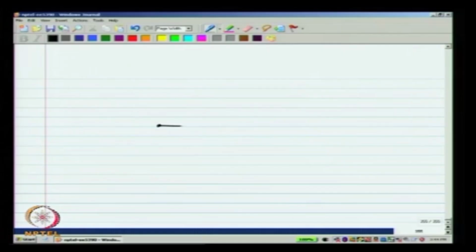Now, like before, like with the single ended fully differential op amp, we have a choice of common mode feedback circuits available. Okay. Now, as I mentioned, there is just too much variety and I will not be able to go through all of them, but I will discuss one more interesting common mode feedback circuit that can be used for the first stage in this case. Okay. It will become clear why it is suitable for the first stage. For the second stage, we will use the conventional one with a resistive common mode detector and feedback using another transconductor. Okay.